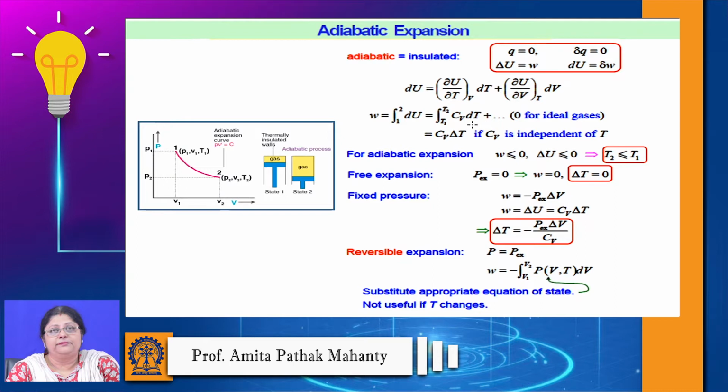Usually we want to take this up in the molar specific heats before we talk about the CP, but before we talk about the delta U, because for delta U we are relating CP to delta U. So the change in internal energy, how we are going to come to this, we are going to look into it. But anyway, if we say that it is CV dT integrated over the temperature from T1 to T2 for an ideal gas, this will be the case. And if CV is independent of temperature in this range, then we can write down CV delta T.